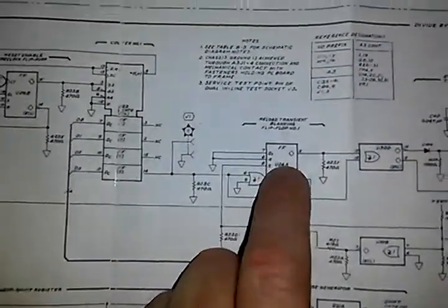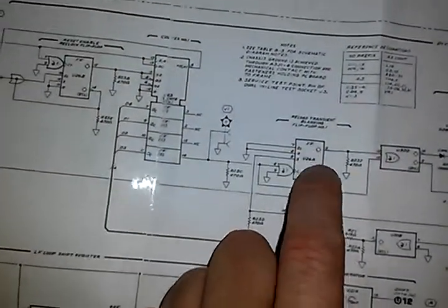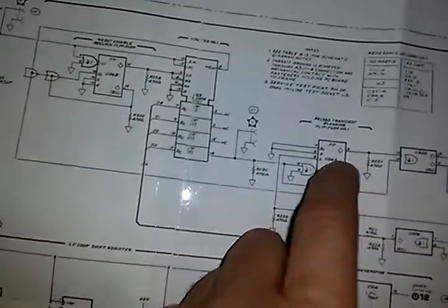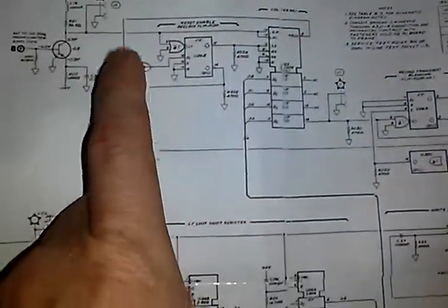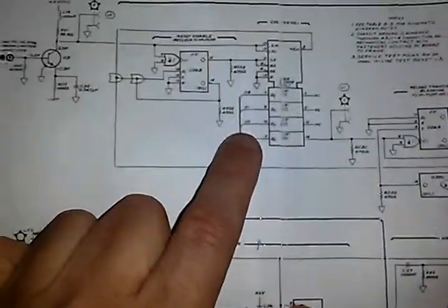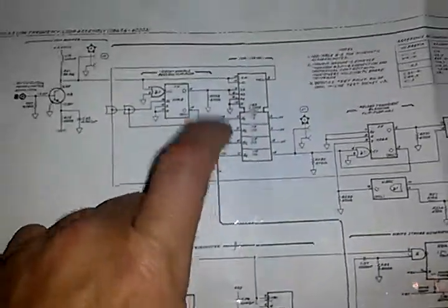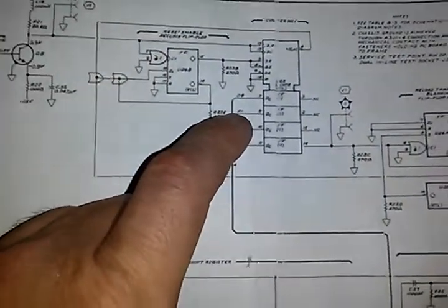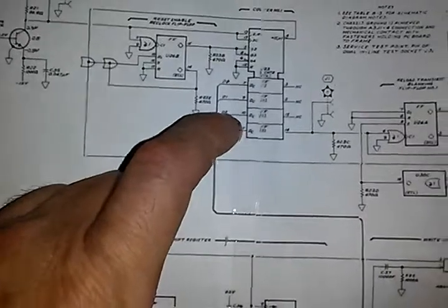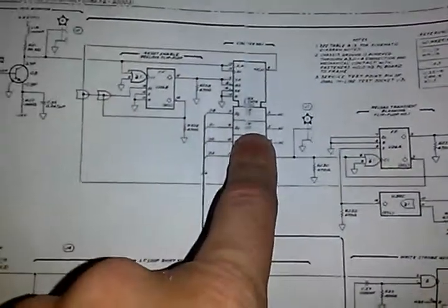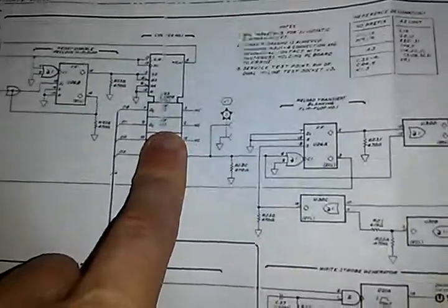Now, what was happening is that this latch was bad. This little latch right here was bad. So it was not holding this line high until the terminal count was achieved throughout the entire circuit, which allowed this chip to essentially reload every time that a terminal count was reached. It reloaded the data on these lines back in, which means that it was not dividing by 16.